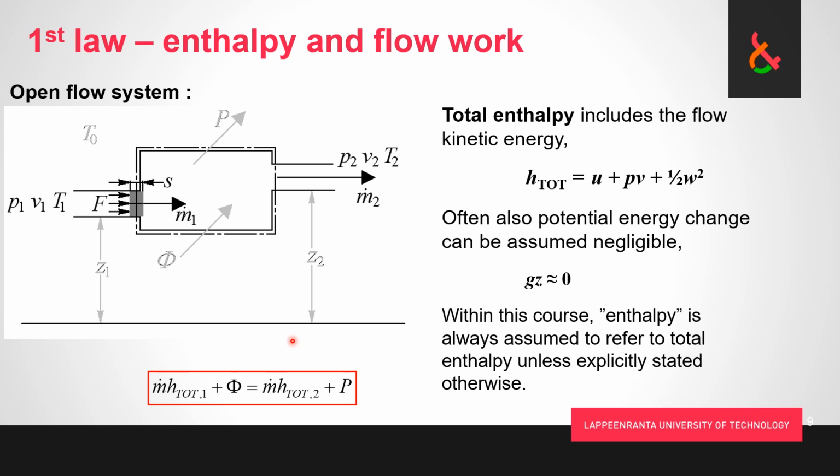So basically, it's a simple enough concept to understand from the perspective that if there is some very high velocity flow, so this term becomes significant. If we actually measure the temperature, we are not going to get a reading for the static temperature, which would be the reading that we got from an imaginary temperature sensor that was floating with the flow and going at the same velocity. We're going to get a temperature reading that includes what happens at the surface of our temperature sensor.